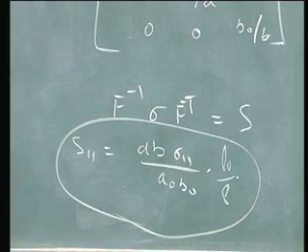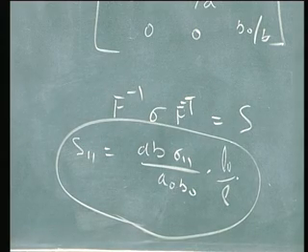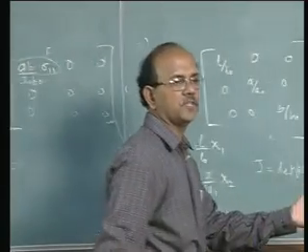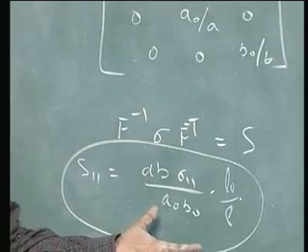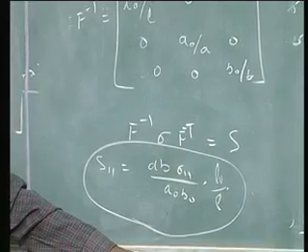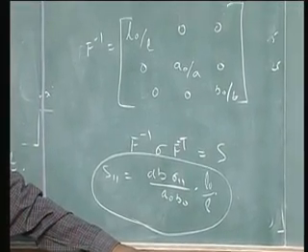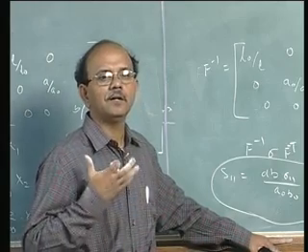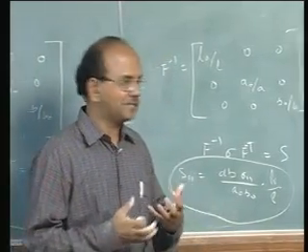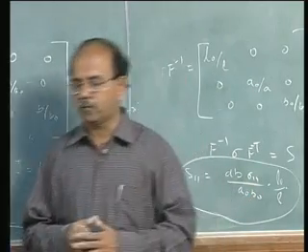So, look at that. Here for P, we were able to give a physical meaning for P, but for second Piola-Kirchhoff stress, we are not in a position to give any physical meaning for it. It is just a pullback operation, and that is how you should view it. You should not look at Piola-Kirchhoff stress as something which we can physically relate to. Yeah, this poses problems.